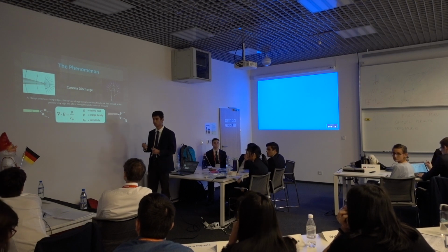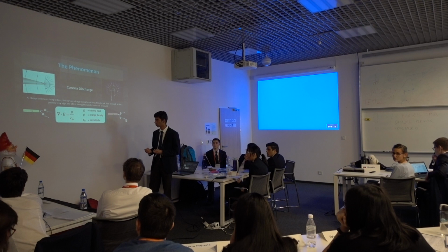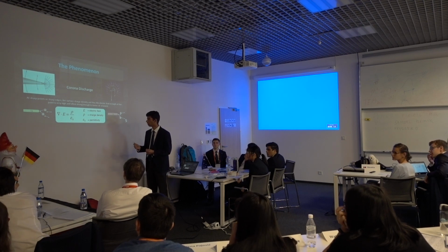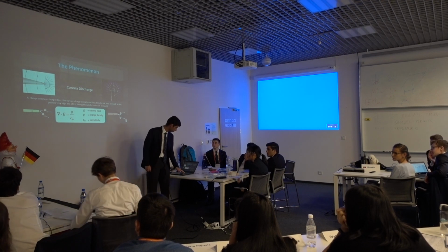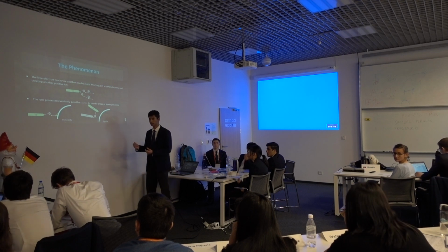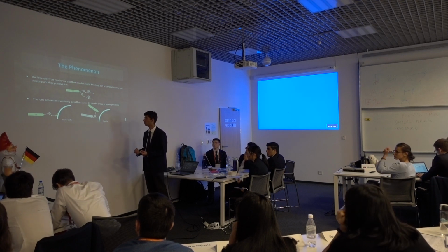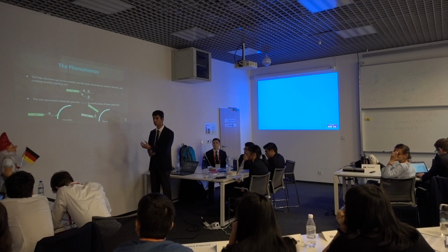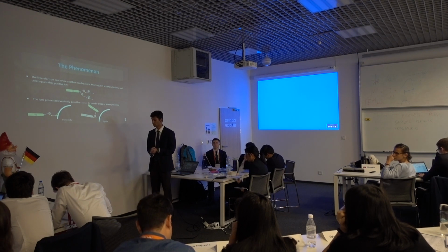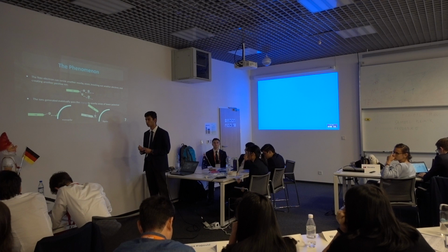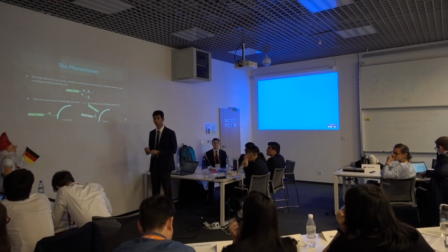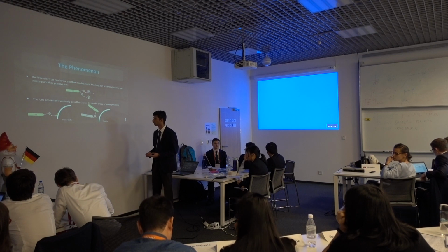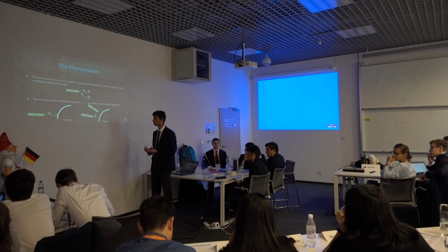After they have been separated, the electron and charged ion are then accelerated either towards or away from the electrode depending on their charge. So the free electron that is out of its orbit will be imparted kinetic energy by the electric field, and if it is given enough kinetic energy, it is able to ionize another atom nearby, knocking another electron out and causing an avalanche effect. These ions that are being created then will eventually pass the charge to nearby areas of low potential.